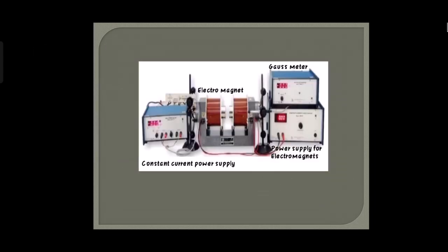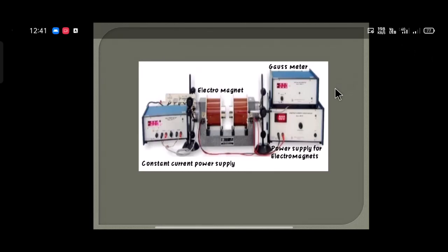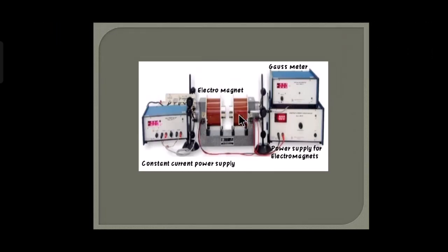For the measurement of the current, place the semiconductor material in the magnetic field produced by the electromagnet in such a way that the magnetic field is perpendicular to the semiconductor specimen. Then, corresponding to that, note the Ix, that is the current in the x-axis, in the reading of the constant power supply.